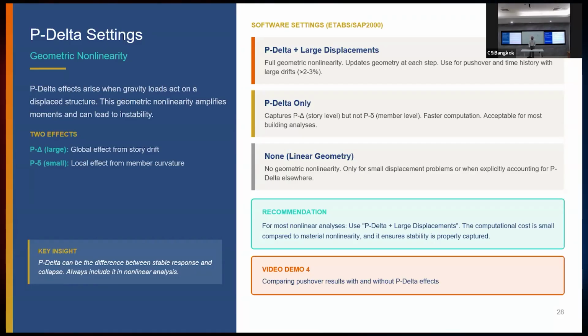For example, the biggest example for them, let's say you have a beam. Now, snap-through. It will be something like this. Can you push this in the center? This is called snap-through. Here it is an arch, right? This one, if I deform it enough, it will become flat like a beam. And then if I deform it more, it will become like a cable.